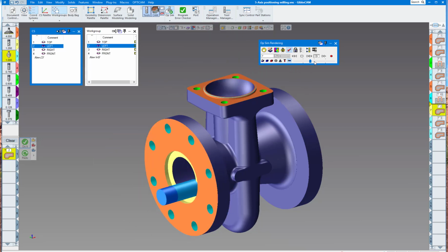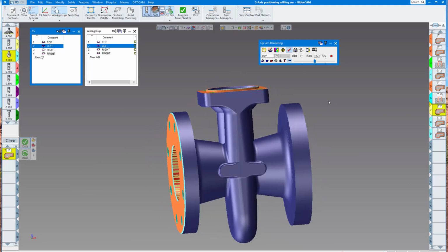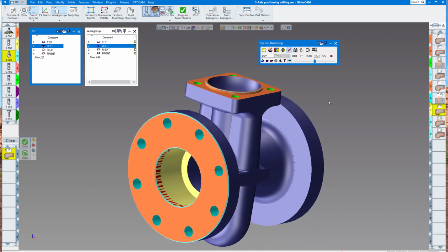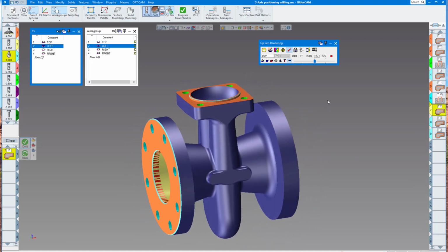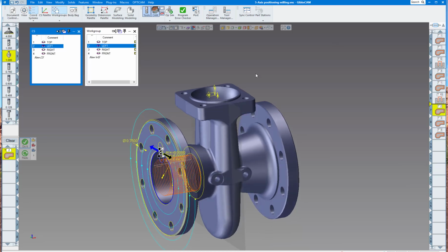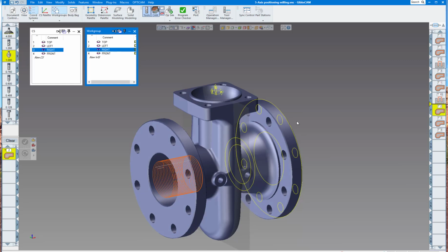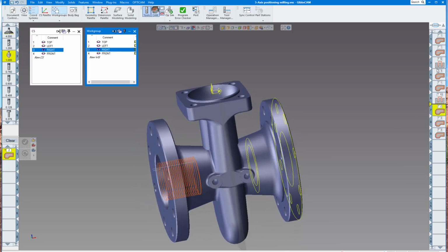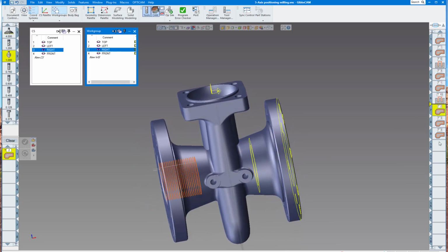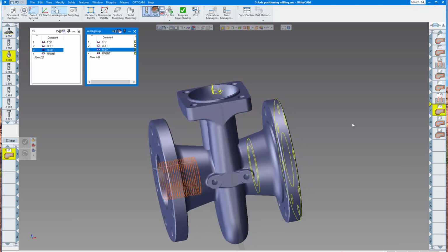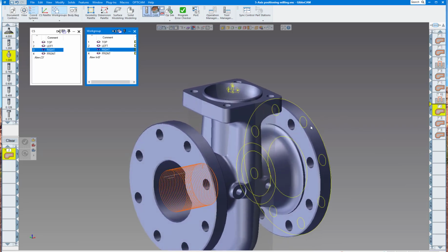There's our helical move inside the bore. Then we come back and we'll stop it and do the chamfers, and there we have our face done here. Now we're not going to do the right hand side just for lack of time, but it's the same process. You can just click on right, and go to the same side. You can actually copy these processes if you'd like and just change it to the right hand side to do the flange on the right hand side.